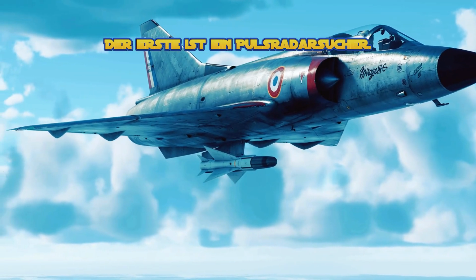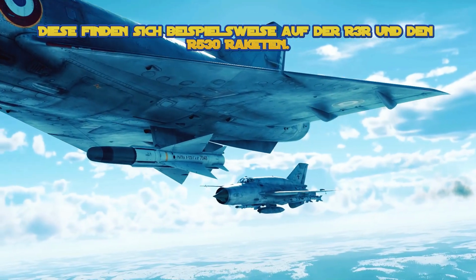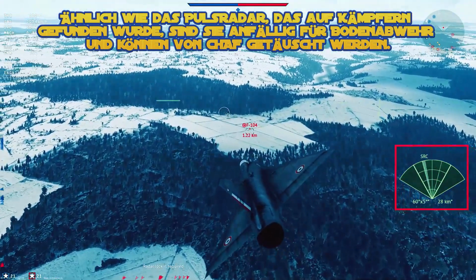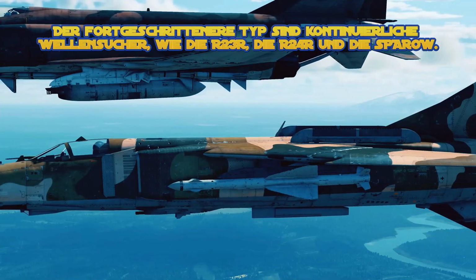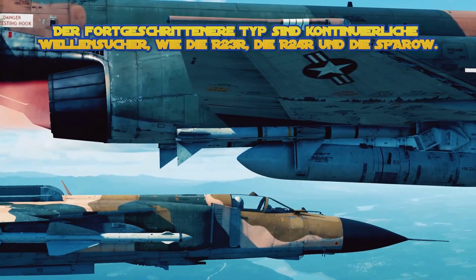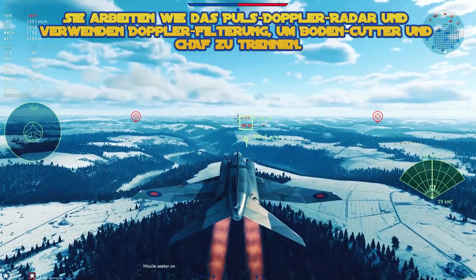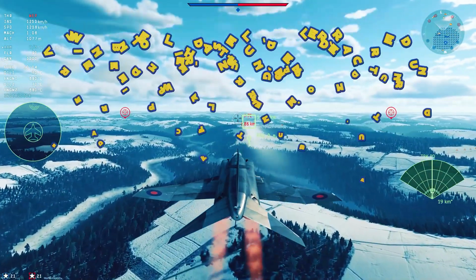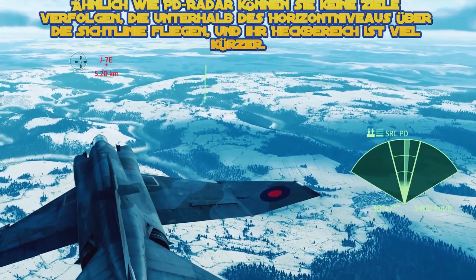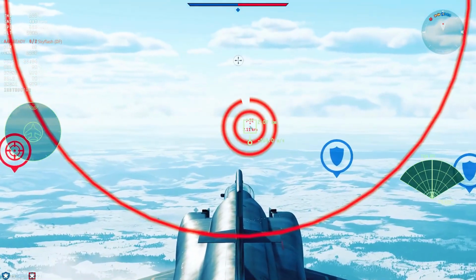The first one is a pulse radar seeker. These can be found, for instance, on the R3R and the R530 missiles. Much like pulse radar found on fighters, they're susceptible to ground clutter and can be fooled by chaff. The more advanced type is continuous wave seekers, like the R23R, the R24R, and the Sparrow. They work like the pulse Doppler radar and use Doppler filtering to separate ground clutter and chaff. Much like PD radar, they cannot track targets flying below the horizon level across the line of sight, and their tail-on range is much shorter.